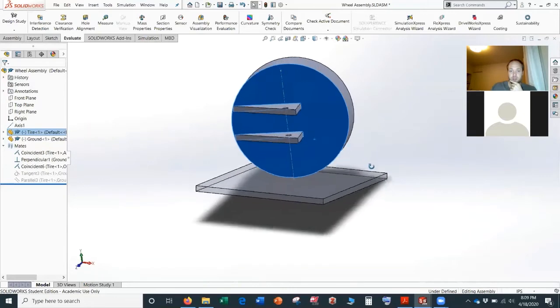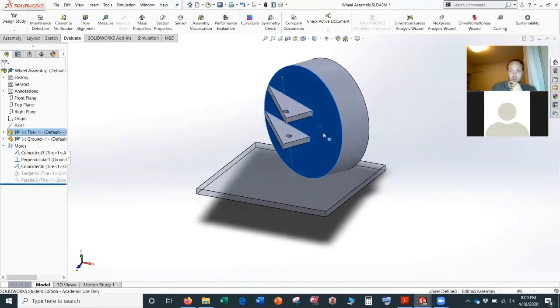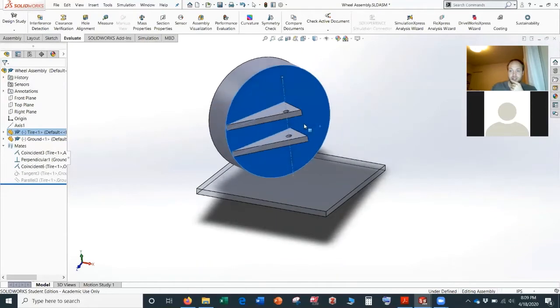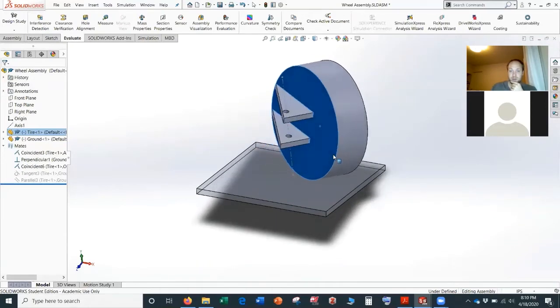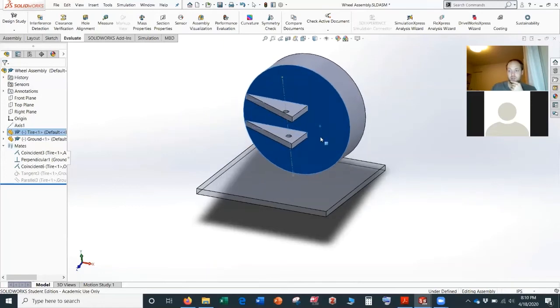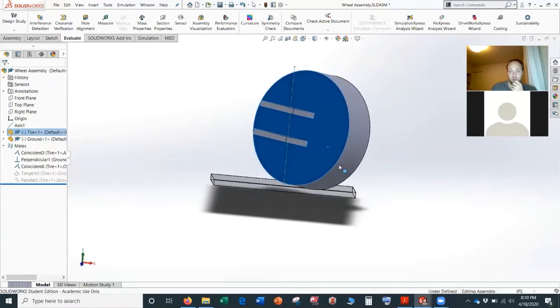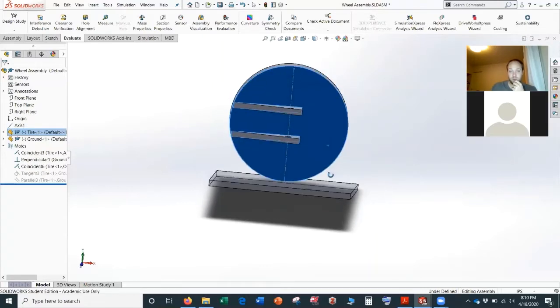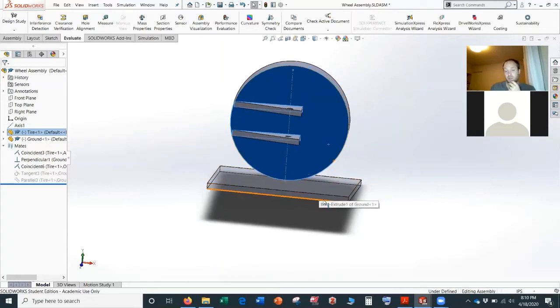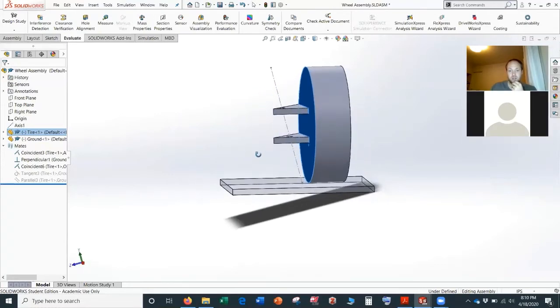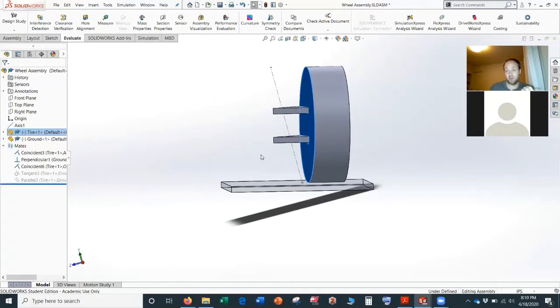of scrub. I mean, the other thing you'll notice though is now as you turn, the tire does scrub across the track, right? So if you're going slow, this might add some tire effort, although I don't think it's going to be super appreciable. The kingpin inclination, if you have too much kingpin inclination, I mean, you're literally raising and lowering the car as you turn, right? So that's going to add more steering effort. So basically kingpin inclination, right? It helps for high-speed stability, self-centering, because when you turn in either direction, it goes down into the ground. But it adds tire effort.